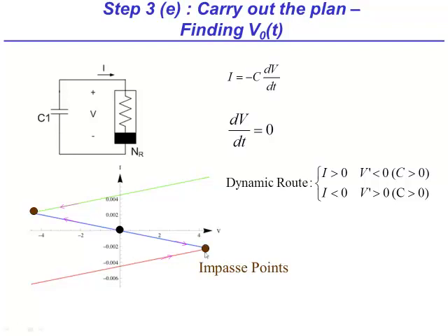The energy for this switching comes from the op-amp power supplies. This is actually the reason why the circuit is called a relaxation oscillator, because of the ultra-fast switching dynamics between the saturation regions and then the slow relaxation dynamics within the saturation region.